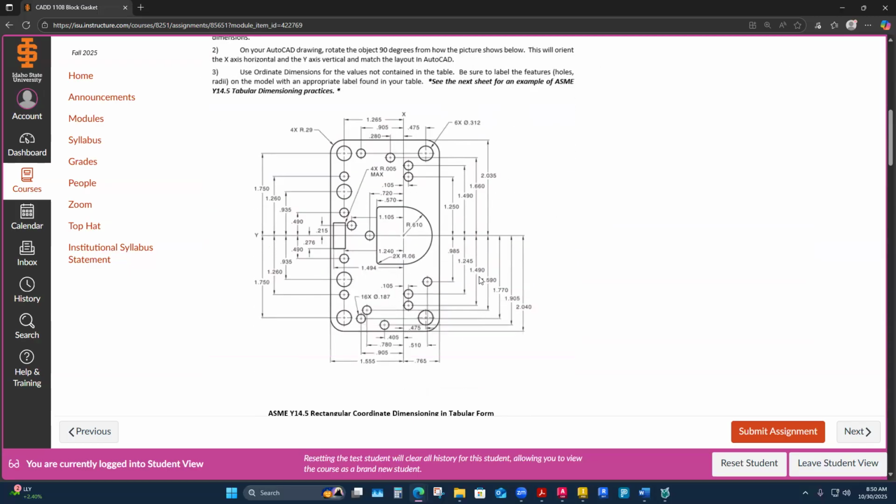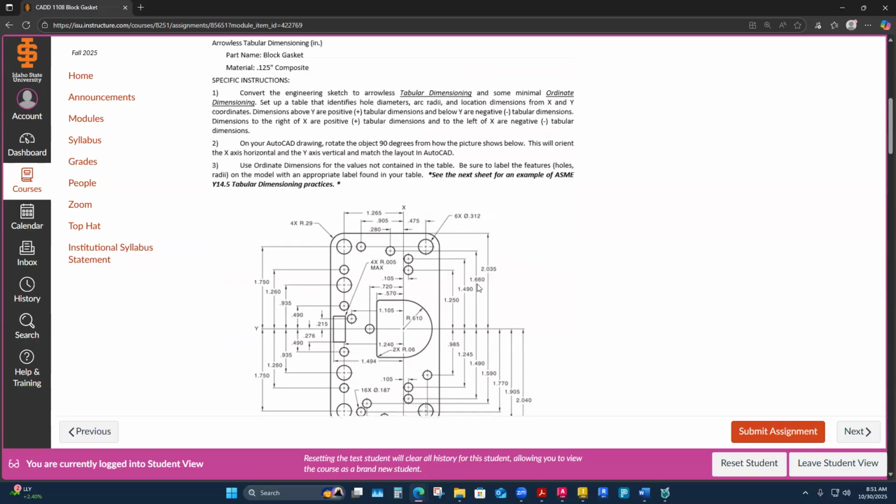So I've been supplied with just our standard dimensioning styles here. I think I determined that, oh, this probably would work. Like if you had dimensioned something like this, it's actually good dimensioning. It's actually not crazy oversaturated, and it probably shows up good on a drawing. But a tabular dimension will be easier to pull dimensions into another program. It's already kind of a little table spreadsheet as a tabular dimension style. So maybe it's easier for someone downstream from you to pull the dimensions from your table into a program.